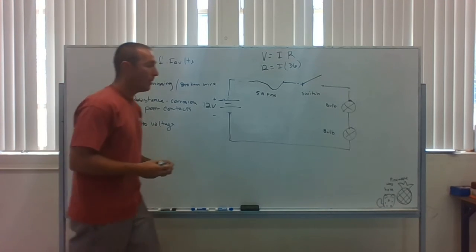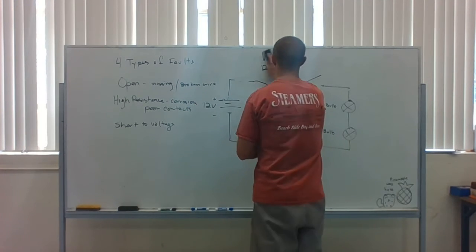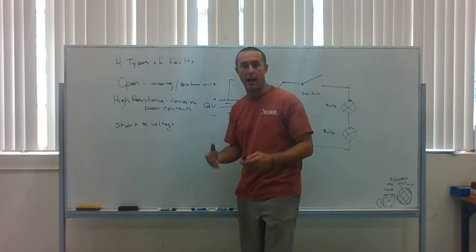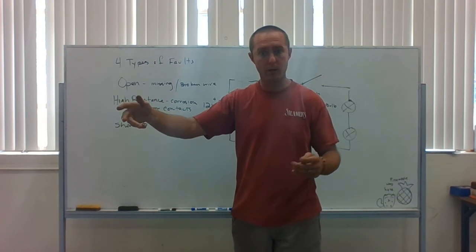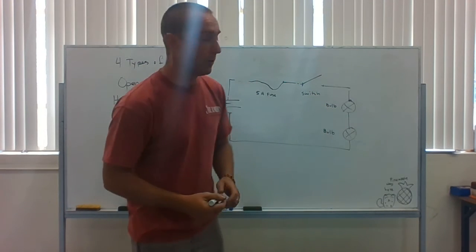Short to voltage. Now, I don't see this one as much. Usually when it's short to voltage, things aren't acting the way you want them to. Like if you turn on one switch and another thing turns on that shouldn't be on that switch. That's the example of short to voltage.